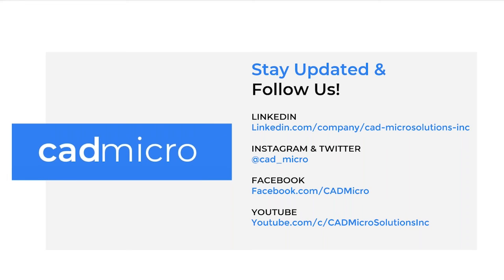Awesome, thank you, Lindsay. And the last question that I have here is, does SOLIDWORKS CAM come with a communication software? That's also yes. So SOLIDWORKS CAM comes with a software called SOLIDWORKS CAM NC editor. So basically what that is, it's an editor that we can open the actual code up once we've posted it out. We can view the code. There is actually a backplot option in there, so we can see a quick backplot or simulation of the actual G code, which is really nice.